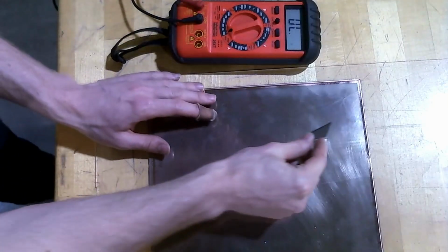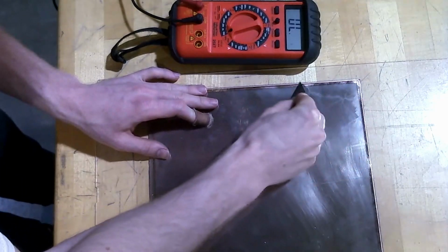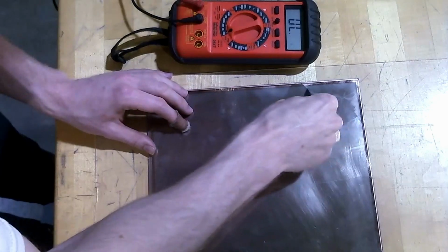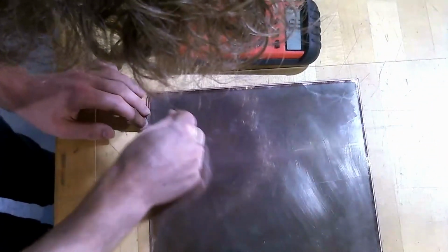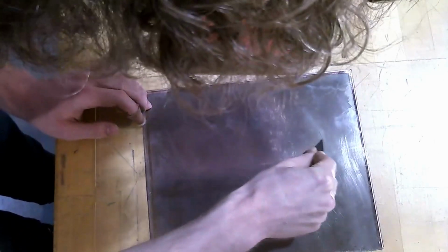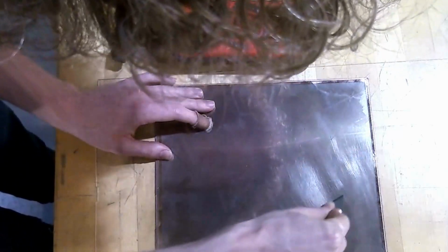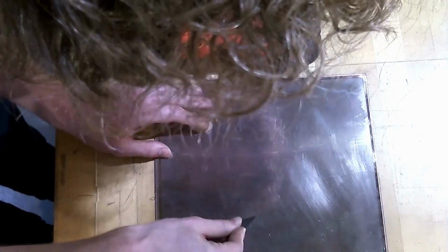The next step is that conductive glass is covered with a layer of polyimide, which has to be scraped away. I would often start this process by going over it with a razor blade to get a good start on it. And then I would use a very high grit sandpaper, so as to not scratch the conductive indium tin oxide layer beneath.